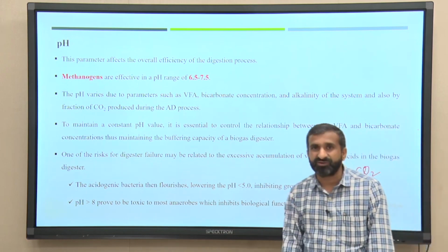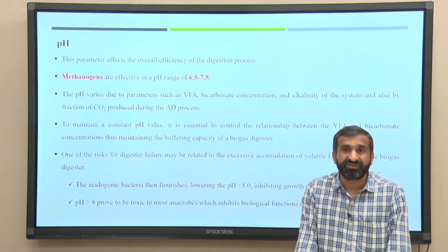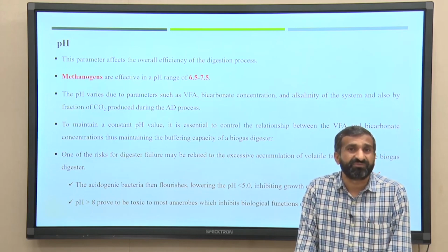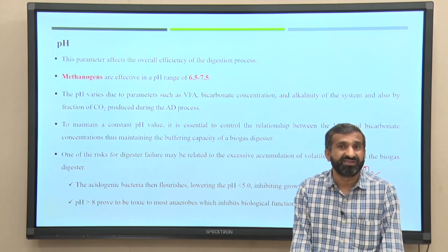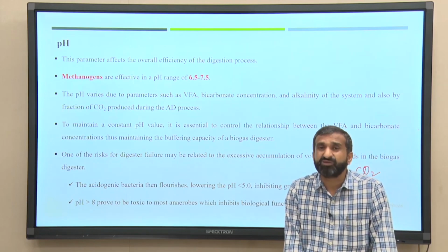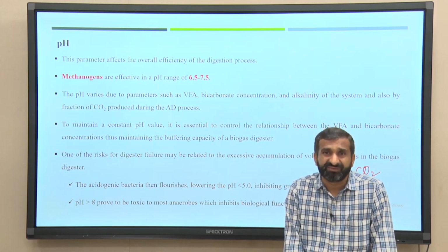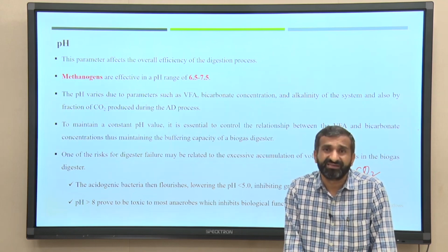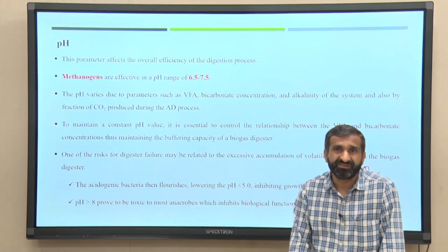So, what is important here is to maintain the pH, and this is possible by addition of a mix of different organic residues. Suppose you are planning kitchen waste, it is good to mix it with other kinds of material which will maintain the particular pH. Or your reactor has to be acclimatized to the neutral pH, and slowly this acidic kitchen waste could be fed into the reactor, not at a very high rate, and by looking at and checking the reactor pH.